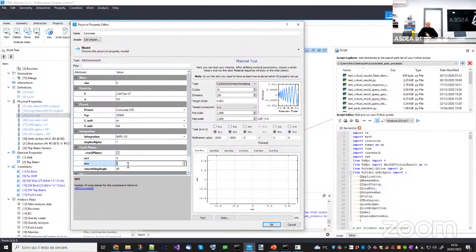Okay, but when the displacement is not smooth, talking about strain is not reasonable anymore. The simple reason is that imagine that you have two different specimens, one like this and one like this. Now the thickness of the crack is independent of the size of the specimen. It depends, for example, in concrete, on the size of the aggregate. So the fracture process zone was something like 2.7 times the maximum aggregate size, because the crack has to pass through the aggregates.